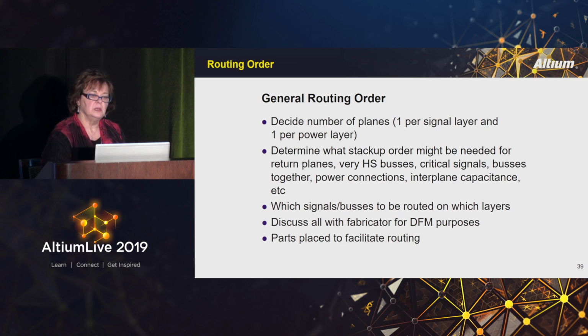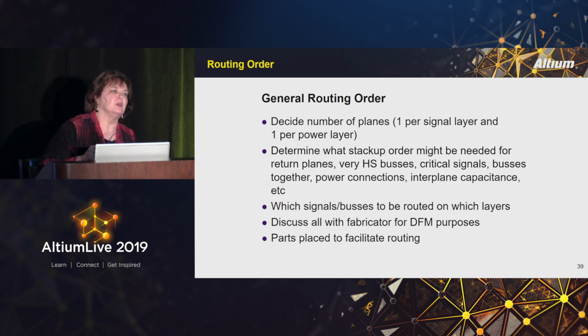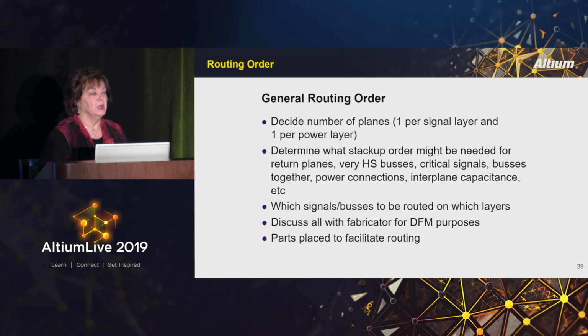And then be sure that you understand some DFM issues as far as facilitating the routing. Years and years ago, I've known Rick for 20 years-ish, he used to say something that made me go, oh, wow. He would say, before he ever put a single route on the board, he knew where every one of them was going to route. I went, how can you possibly know that? But now I do it, so now I know. You have to plan this stuff out ahead of time and know where you're planning to put things and how you're going to have that stackup work.